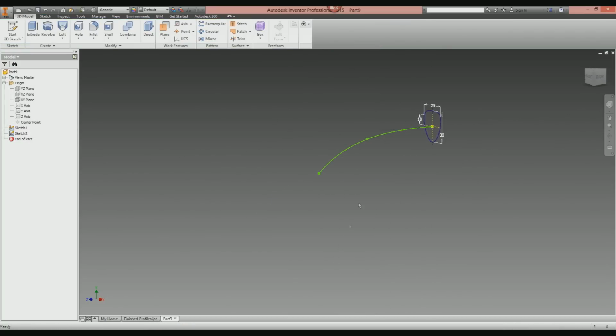I'm going to finish that sketch, and the next thing I need to do is to create my second profile, the one that's going to start the loft. This is the termination profile. I want to create a new profile around about here. How do I do that? I've got nothing to sketch on. Well, I need to create a work plane.